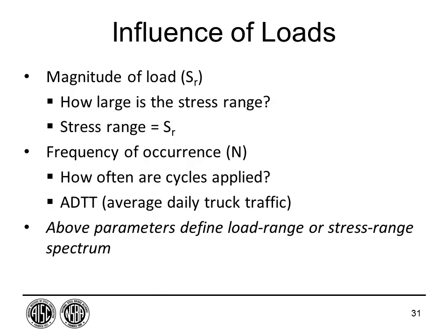So what about loading? That's kind of resistance, but what about the loading? Well, the things we worry about is the load itself. How big is the stress range it produced? That's the stress range. But it's also time dependent. So how often does this happen? And again, as we said earlier, it's really the average daily truck traffic that we worry about. Cars and light trucks, they really don't cause damage.